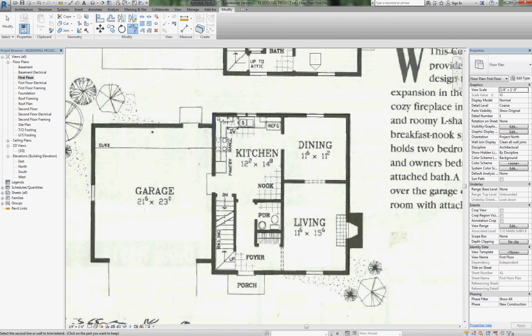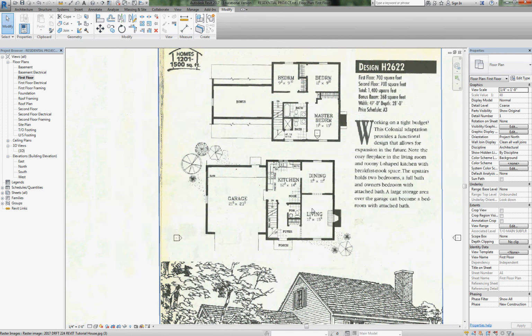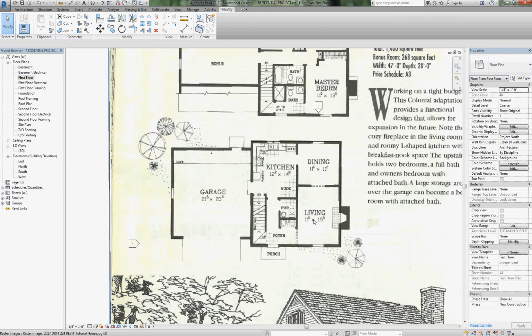We know our house then is 25 feet plus a 22-foot garage. So we've got modular numbers here. We're going to work to the nearest 2 feet where possible, or 1 foot by design. So this one was obviously designed to be 25 feet. So now you can see we've got the image scaled to what we need it to be, and we can start drawing walls on there.